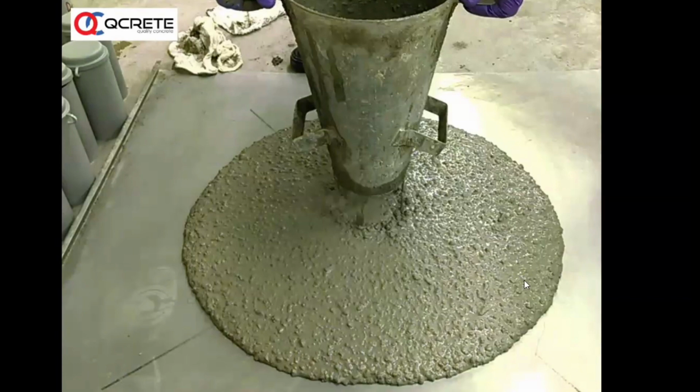This is not a slump test, and you can see how the mix looks cohesive. There should not be bleeding here. These are the things that you have to observe when you are receiving the concrete. That's what I am talking about, the precautions that you have to take after you produce the concrete and receive the concrete. You can see here there is no bleeding, there is no separation of water. So that is the beauty of such concrete. It has to be designed in a proper way.